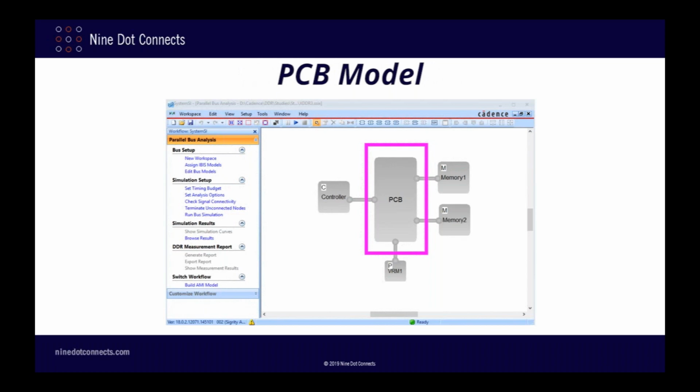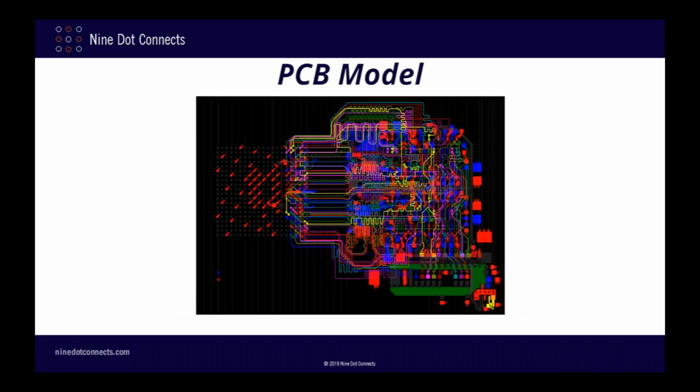Since the PCB connects all of the other components together and carries the actual electrical signals, it obviously needs to model the actual copper traces and planes of the PCB in a way that lets us determine just how these electrical signals behave as we perform our high-level analysis. As you can probably guess, this means that we need to do a low-level frequency-based simulation that will derive a set of S parameters that we can plug into this model. System SI can then use these S parameters in conjunction with the pin models in the IBIS files to simulate the behavior of the actual signals.